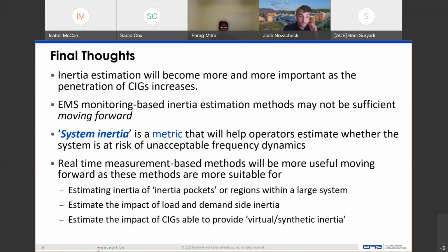So if you look at the aeroderivative turbines, the ones that you have on the wings of Boeing 777, they have the low pressure turbine on a different spool. So the low pressure turbine and the high pressure turbine are not on the same spool. Now, what happens because of that?